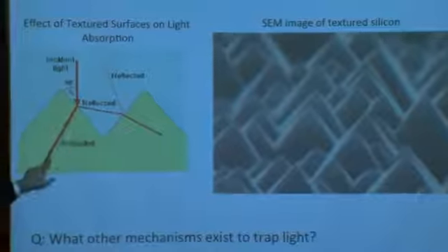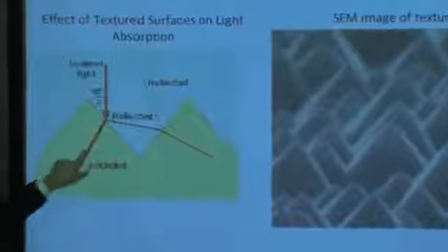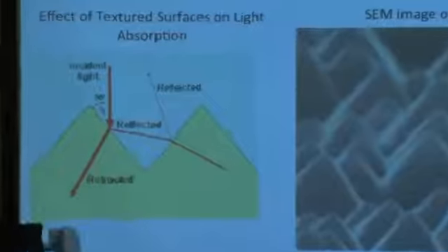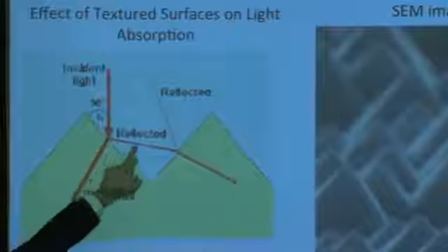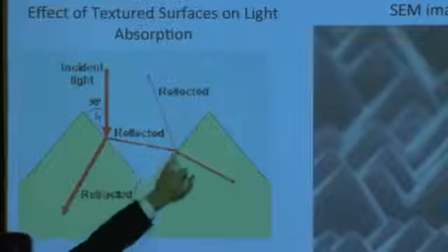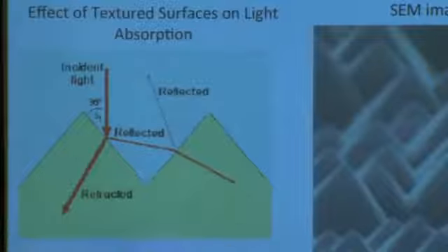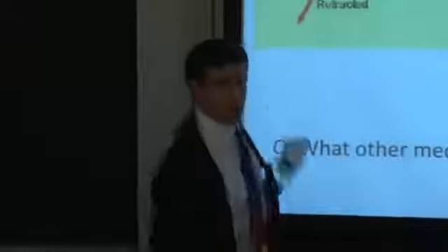So the light comes in for the textured surface. Some of it goes into the device. Notice that Snell's law is in effect, so the light bent or was refracted. And some of the light is reflected off the surface. Now, because of the texturization, you get that second chance absorption. So the light has 2 bounces before leaving, which means that the probability of the light getting absorbed is 1 minus R quantity squared, right? And so you get an enhanced absorption.